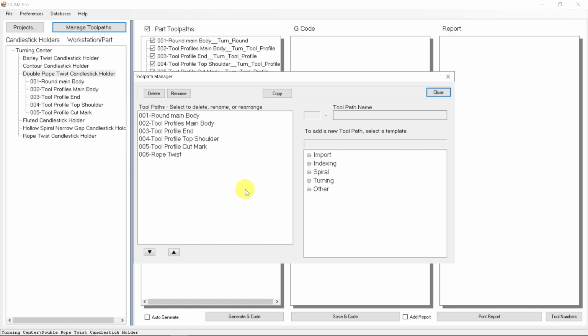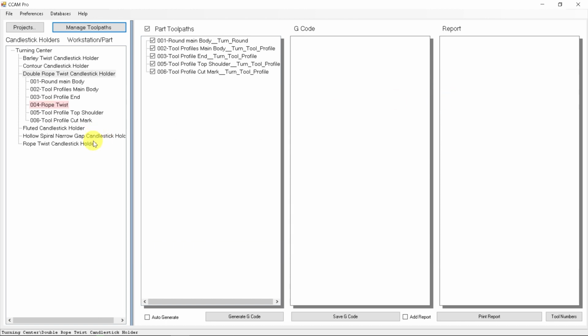But we're going to add that, and here we have the ability to control the order sequence. So if we come up here and put this right before it machines the 2 flat processes with the 1/4" cutter, that's exactly where we want it. So I'm going to close that off, and now it's highlighted saying we need to input some parameters.